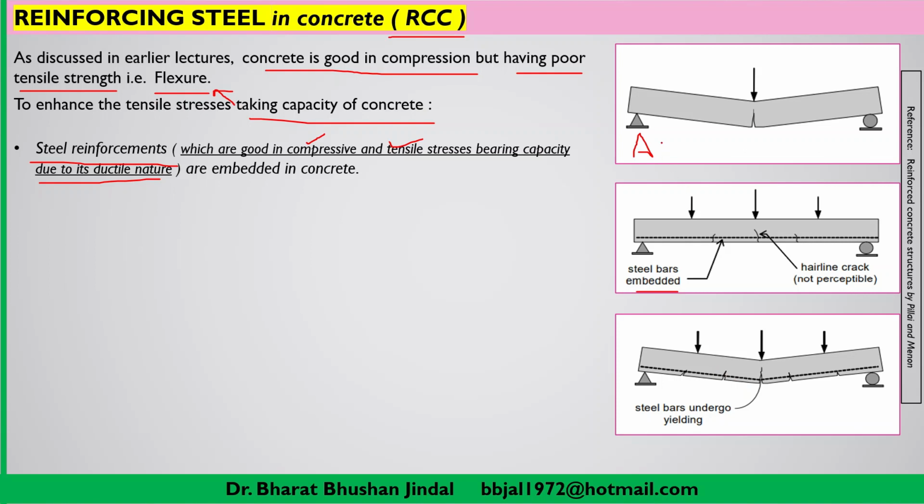So in figure A and figure C, if you compare, figure A will fail at the load which we are applying in figure C. Here we have shown only a single load, and here we have shown three loads, so you can easily compare figure A and figure C. A purely concrete structure can take a very small amount of load, but the same beam, when reinforcement is provided, becomes an RCC beam, and its load carrying capacity is significantly improved.